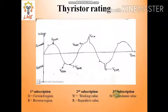The third subscript M is the maximum value. So VDWM we can say is the maximum forward working voltage. M stands for maximum, D stands for forward region and W stands for working value. That is why we call it maximum forward working voltage.